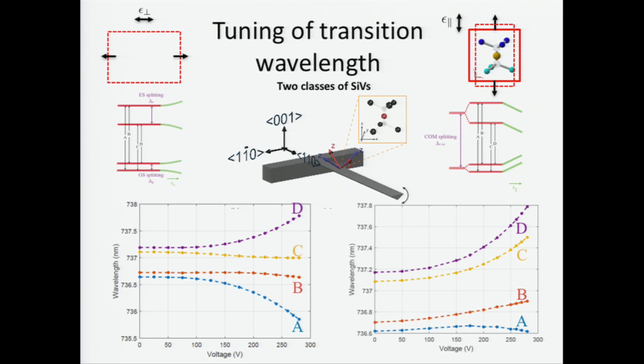This is the sample we make. The top surface is what you get with your substrate. Your sample has a face that is fixed, 0 0 1. But the 1 minus 1 0 and 1 1 0 directions are under your control. You can do a rotation of your GDS file. But you don't control the silicon vacancy orientation. You have four possibilities. Exactly. In this case, I am using these four arrows to represent the four possible orientations.